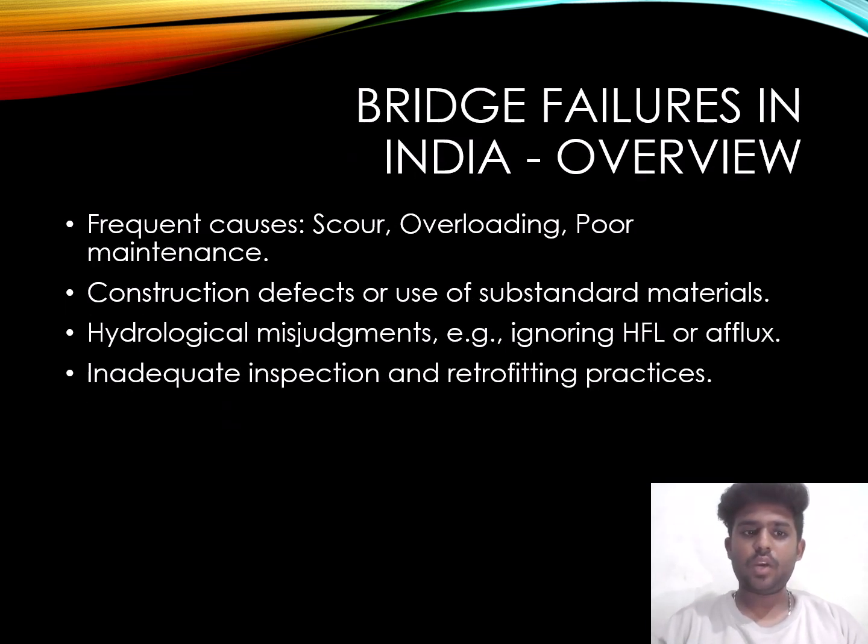Bridge failure in India overview. Frequent causes: scour, overloading, and poor maintenance. Construction defects or use of substandard material. Hydrological misjudgments, for example ignoring high flood level, HFL, or afflux. Inadequate specification and retrofitting practices.